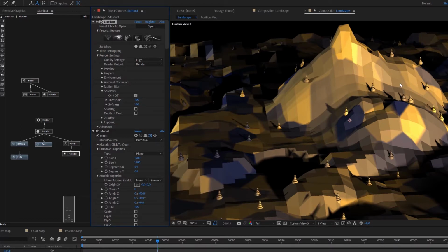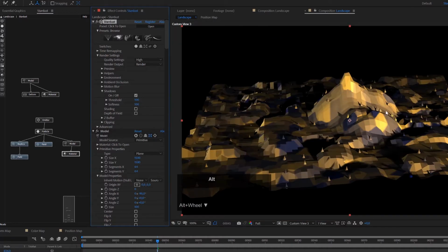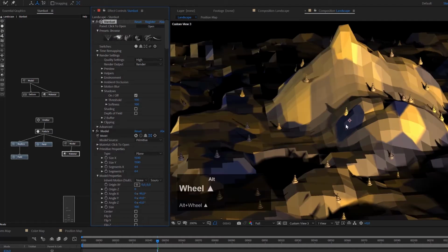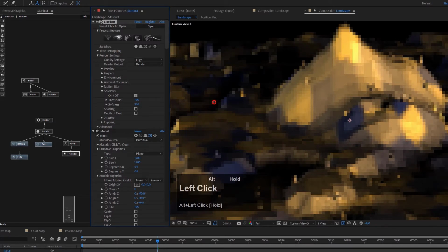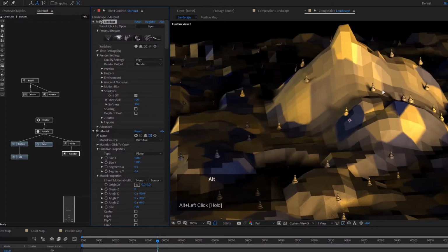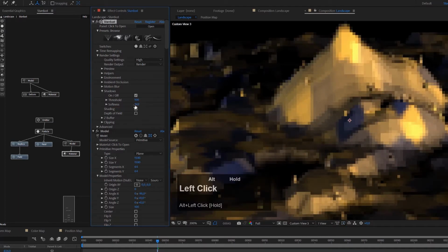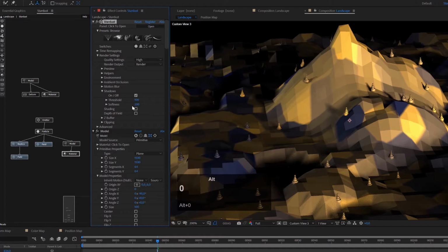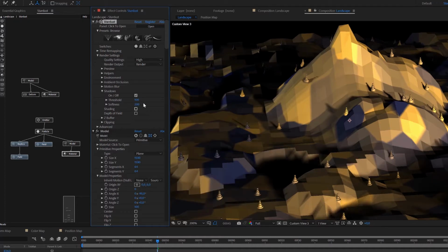This is because my lights that I have in the scene are now creating shadows. And you see that this makes it look really realistic and really cool. So not only my small trees are creating shadows on the surface, also the surface itself. So these canyons here, these valleys now are filled with shadows. And you can of course also change the softness, so I can really make these shadows very soft. And you see that this also changes the look here quite a bit. So let's reduce this again, maybe to something like 200, that they are a little bit softer.